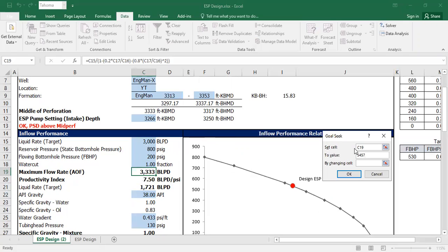In the well modeling software, I created an analytical IPR, a theoretical IPR. I used permeability and thickness to generate the analytical IPR, and it gives me the productivity index value and the maximum flow rate value. And the maximum flow rate value, without knowing the flowing bottom hole pressure, is 5,457. So I will instead calculate the flowing bottom hole pressure so that I get this value. Click on OK.